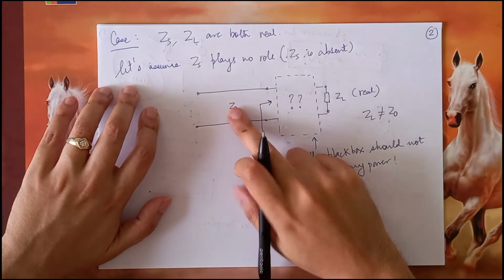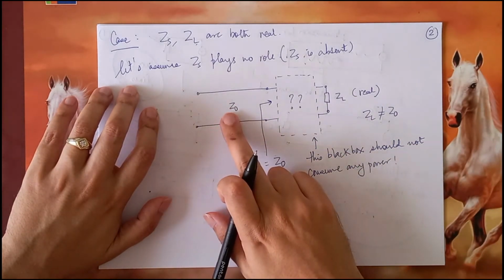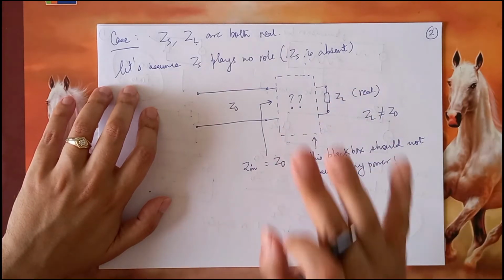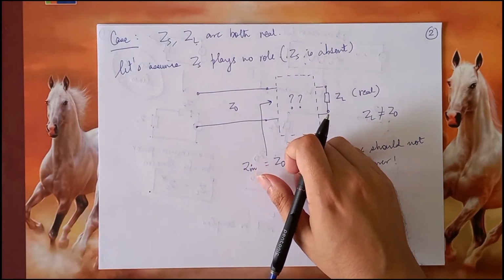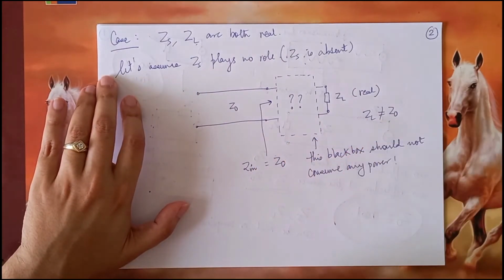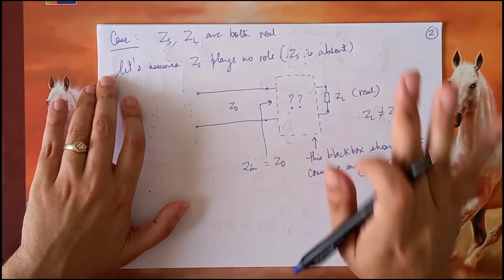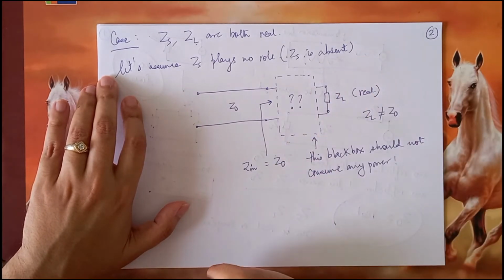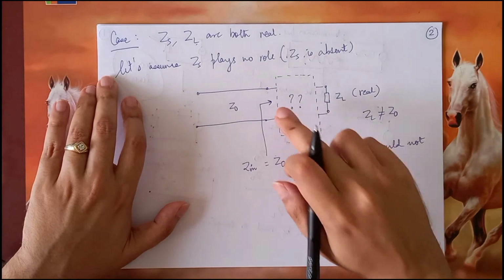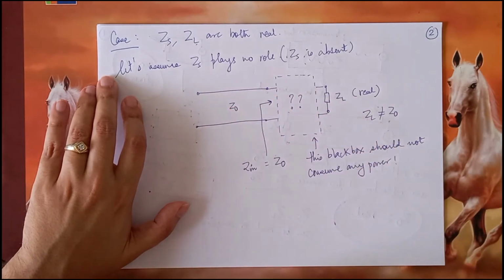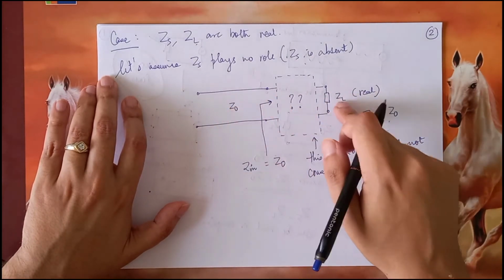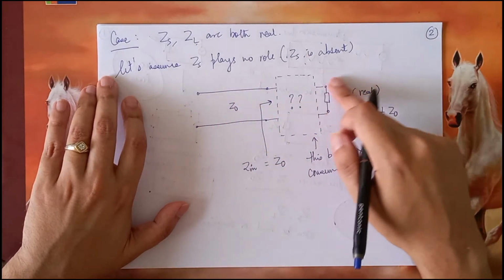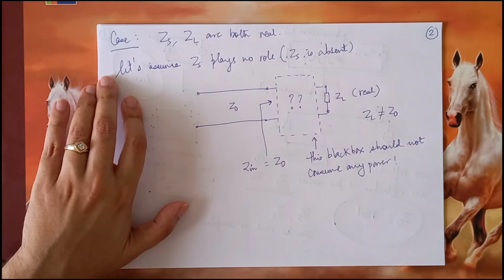Thereby, it is sort of tricking the transmission line into thinking that the load impedance indeed is Z0. But there is no magic over it. It is not merely a trick. It should not just trick this transmission line, but it should also ensure that all the energy or the power goes to this load impedance.